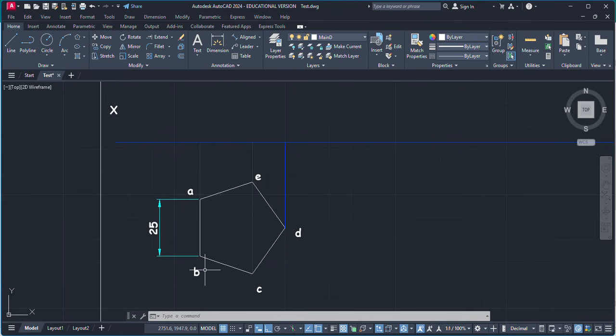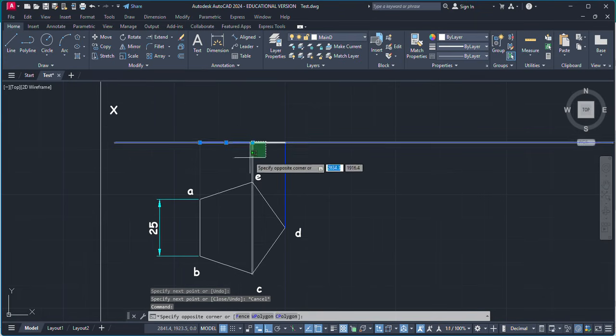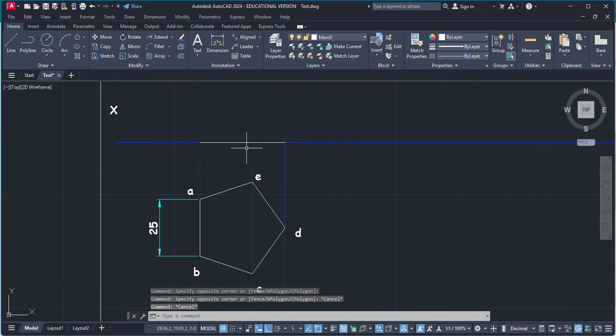So the line will appear from here to here. It will be the starting point, this will be our end point. So from here to here. Now instead of creating a single segment, create multiple segments from this point to this point, then from this point to this point. I will tell you about the use of this multiple segment. Now our front view is created in two segments, first one and second one.